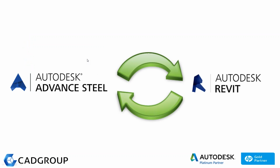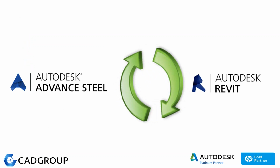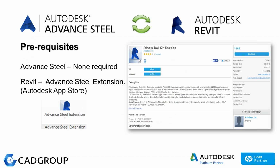The first area we're going to have a closer look at is going from Revit to Advance Steel, and the synchronization that we'll get between those two applications in our workflows. A couple of things before you get started, more so on the Revit side. Advance Steel has no prerequisites, the tool's already on board, whereas inside Revit we need to at least get the Advance Steel extension, which is downloadable from the Revit App Store.